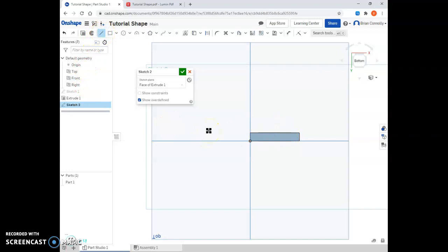Before I used rectangles and circles, and you can use polygons for all of this. Another way to do that is to move and use the line tool. And you'll notice that a little line to the right of my mouse shows up. That's telling me that it's vertical, which is good. Then I'm going to move my mouse again, and I have a horizontal line right there that's telling me that I automatically have that constraint in there.